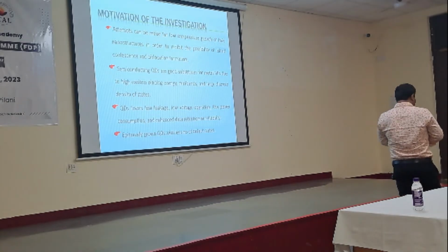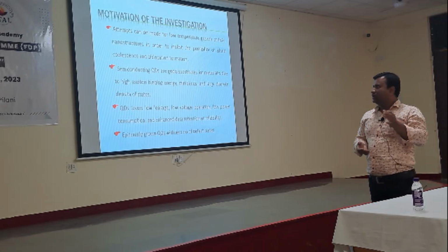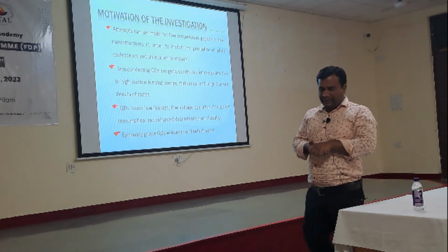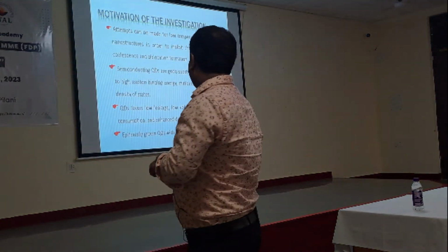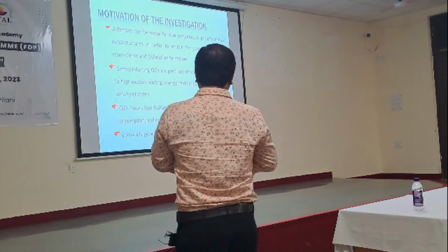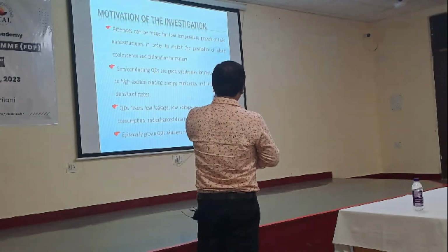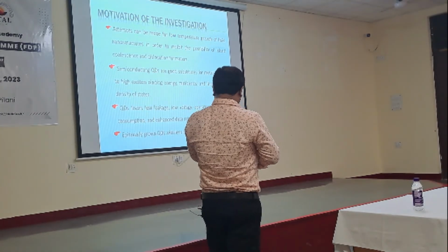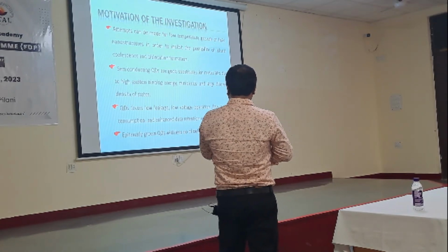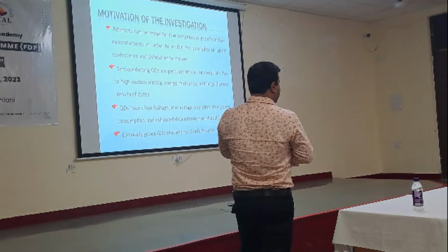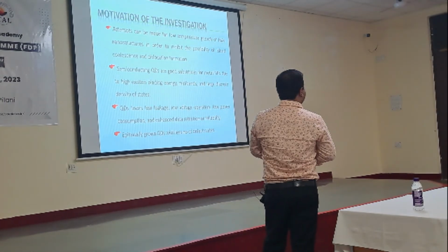In this case you have to realize that when you go from bulk to nano, the size of the particle will be at least comparable to your excitonic Bohr radius or de Broglie wavelength, right? I will show you the calculation. Now, quantum dots also favor low leakage, because the discrete energy levels are responsible for storing the charges. Low voltage operation and low power consumption will be achieved, and epitaxially grown quantum dots are generally considered to have very few defects.